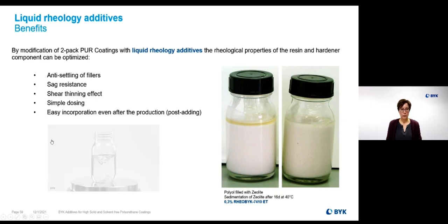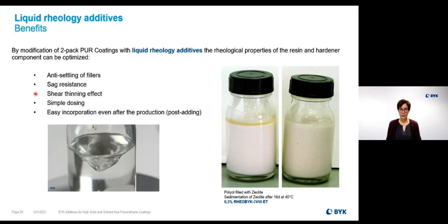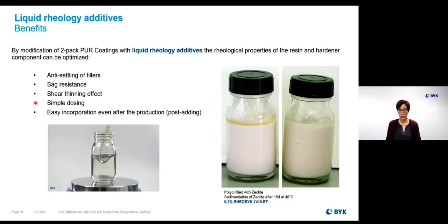We can use these products for anti-settling of fillers and for sag resistance. We have a strong shear-thinning effect. And the good thing about these products is that they are easy to handle and easy to dose. So even an incorporation after the production, in post-addition, can be done.